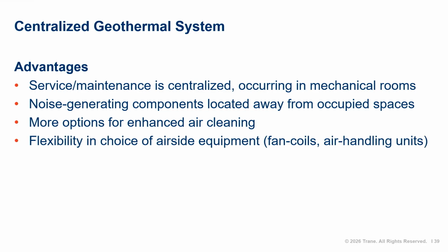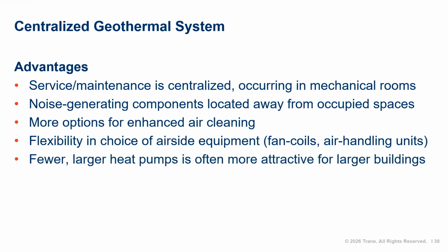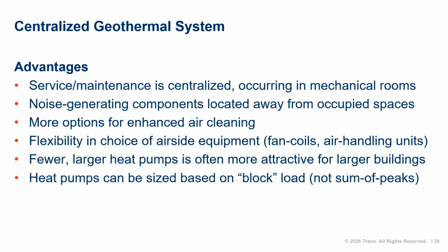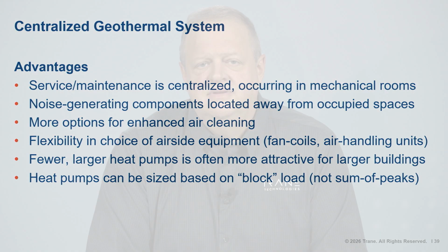Now, on that theme of flexibility, a centralized geothermal system can pair with almost any type of airside equipment, from fan coils to air handlers. And using fewer centralized heat pumps often makes this the more attractive choice for many larger scale buildings. And finally, the centralized heat pumps can be sized based on the block building load, which results in fewer installed tons than simply summing the peak loads of all the zones, like with distributed heat pumps.